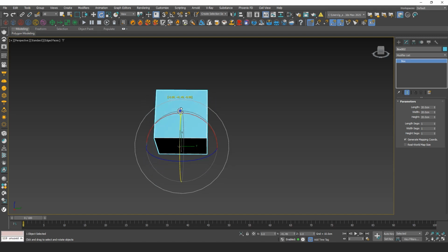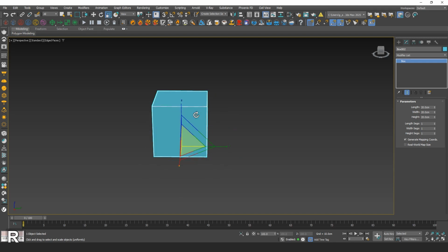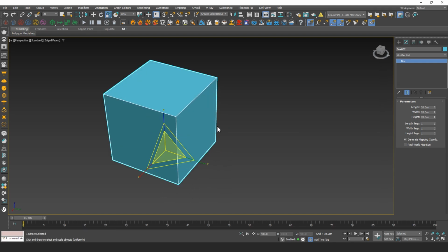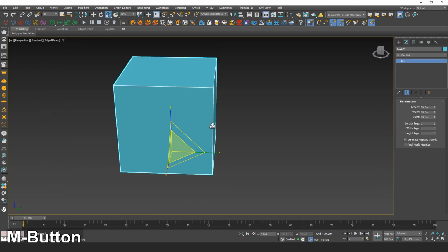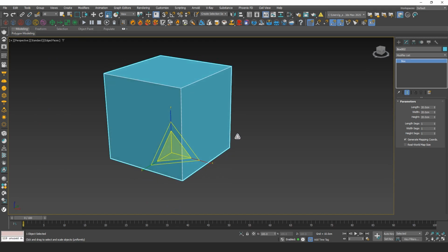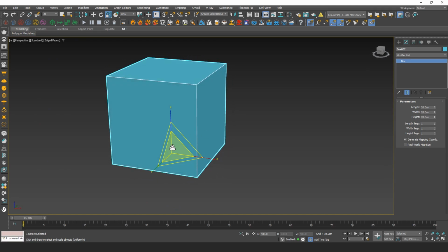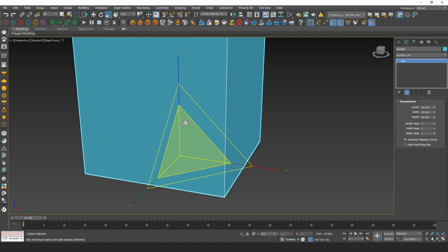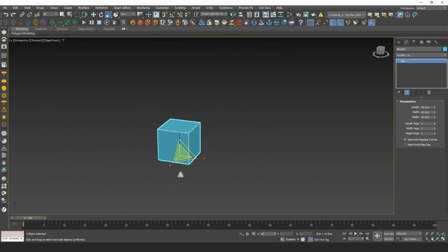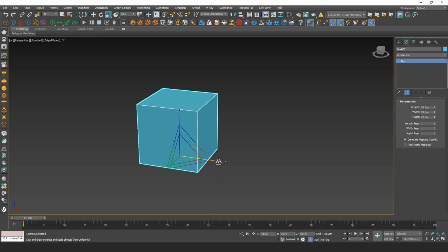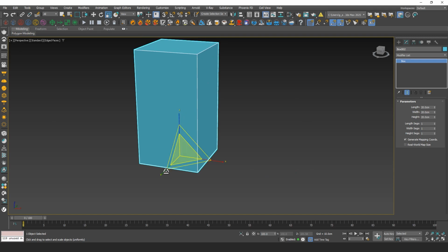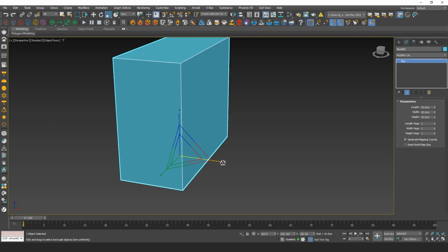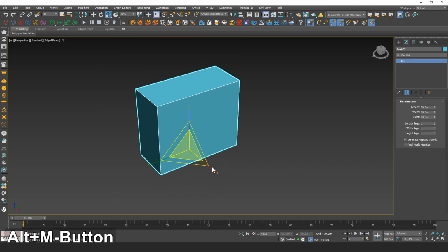To resize an object, press R, which will activate the scaling gizmo. There are 2 ways to scale an object: uniform scale and non-uniform scale. First one allows for proportional resizing. Drag the center of the gizmo upward to enlarge the object or downward to shrink it. Non-uniform scale lets you stretch or compress the object along a specific axis by dragging the respective axis individually. Try scaling objects in different ways to see how the proportions change.